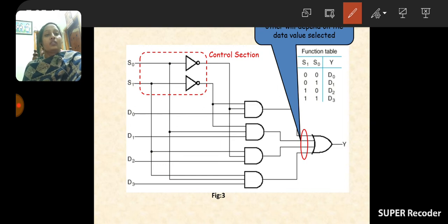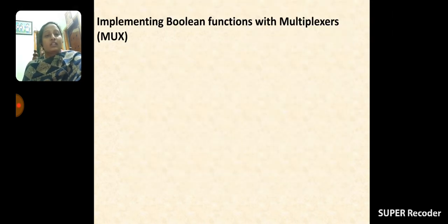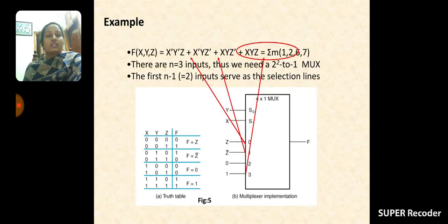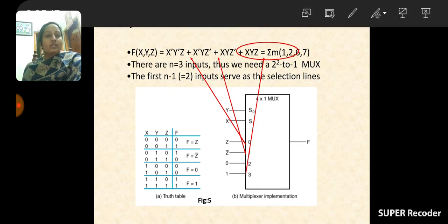Okay, so now we move to the truth table. So once see the truth table. This is the truth table, I already explained. See here, already I told that without the enable signal, here the enable signal is considered as X. Without the enable signal, the output should always be equal to 0. After application of the enable signal, the output must change.